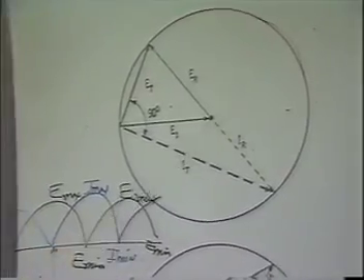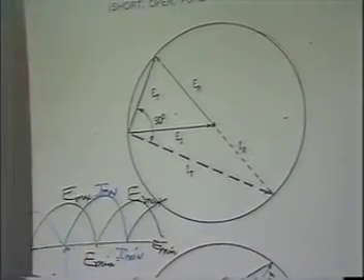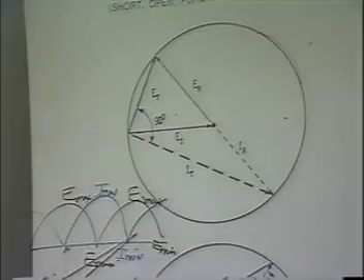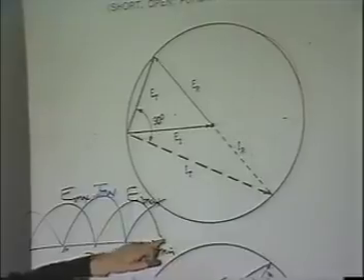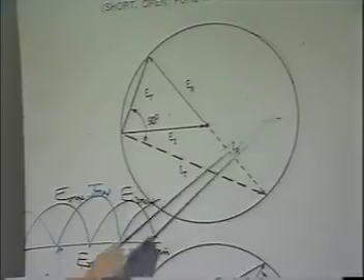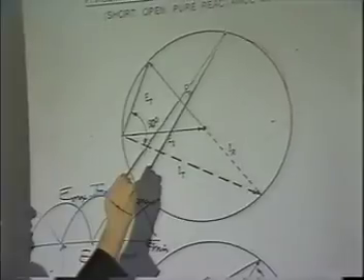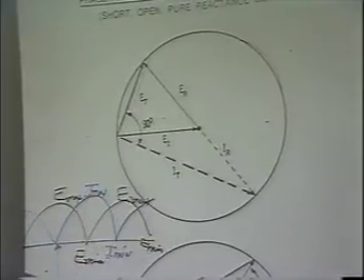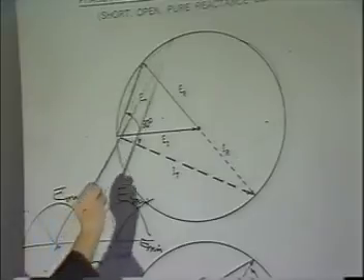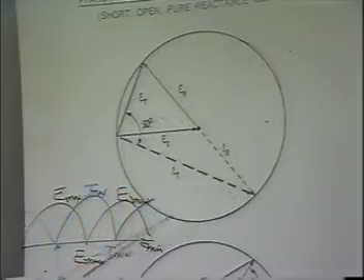On this chart, what are they going to be? They have to be 180 degrees out at all times, right? Because there's twice the angle up here as there is here. Now notice on this transmission line, if it's terminated with a short, or terminated with a pure capacitance, terminated with an open, terminated with an inductance, E sub R is always equal to E sub I. You trace out this outside circle, no resistance at all, pure reactance. And in that case, the voltage and current, total voltage, total current, is always plus or minus 90 degrees. Always plus or minus 90 degrees.